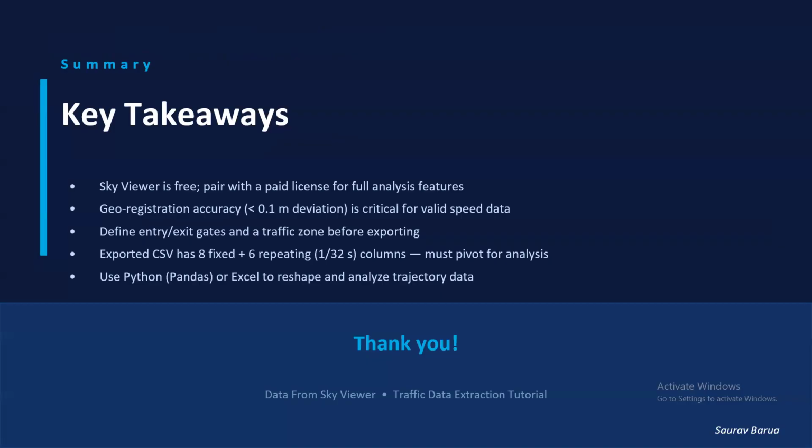And what is the takeaway? Data from SkyViewer is free, but it is paired with the full analysis feature that is license based. Georeferencing registration accuracy is critical for valid speed data, so we have to maintain it. For my study, I use 0.1 meter deviation. We have to define the entry and exit gates and traffic zones before exporting, and we have to export the CSV file.